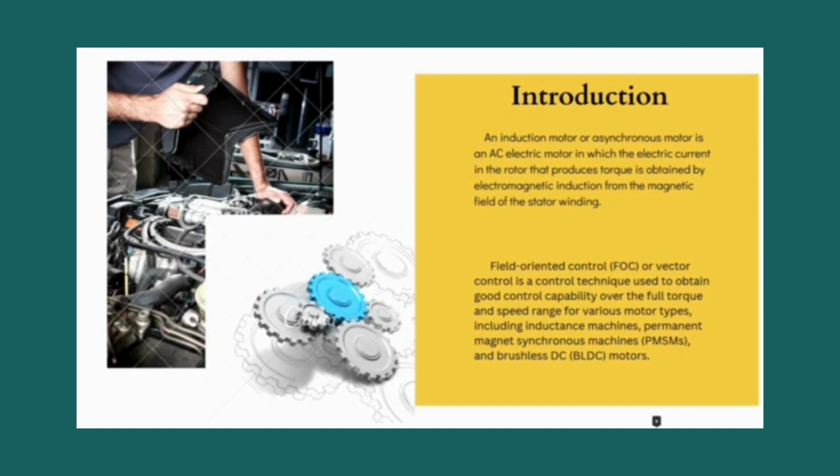FOC, from the full name field-oriented control or vector control, is a control technique used to obtain good control capability over the full torque and speed range for various motor types, including induction machines, permanent magnet synchronous machines (PMSMs), and brushless DC (BLDC) motors.